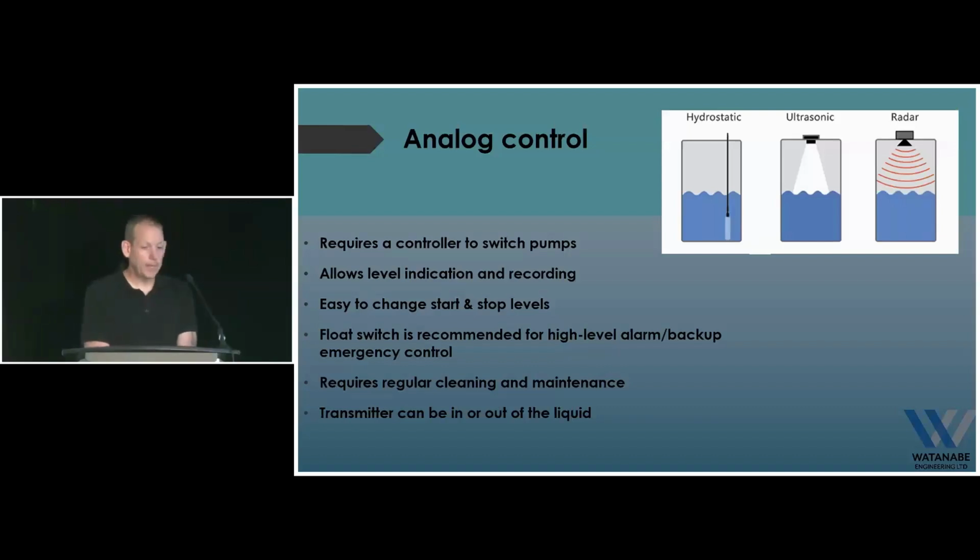We always do recommend putting in a float switch in addition to some sort of analog transmitter, just in case that transmitter fails, because, hey, it's still an electronic piece of equipment, it's going to fail. But the beauty of that is it's a high-level float switch, and it's going to be out of the liquid the whole time. It's only ever going to tip when something goes wrong. So you're not going to have that kind of ragging or greasing up problem that you have with the fully controlled float switch system. It does require regular maintenance, because depending on which technology you choose, there are some maintenance issues that you need to take care of.